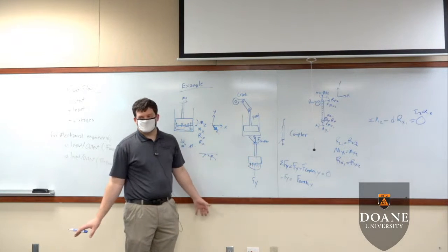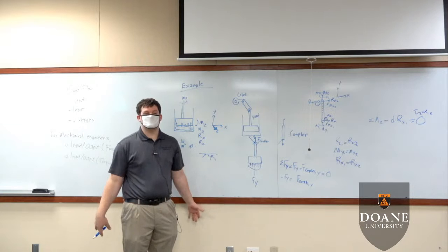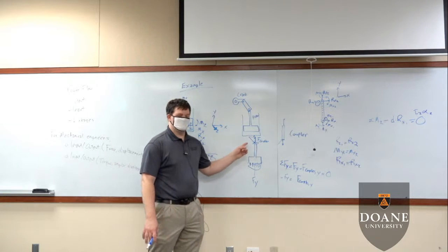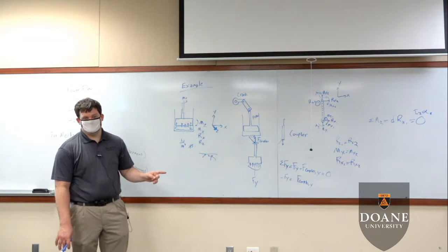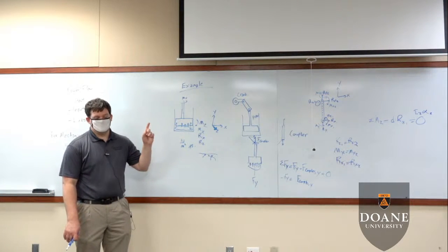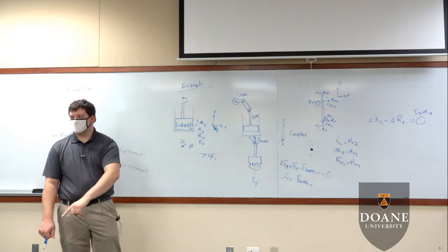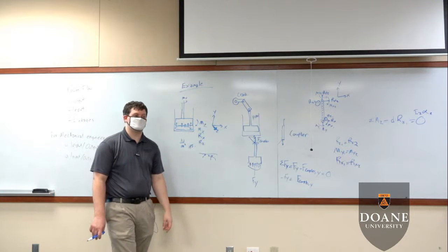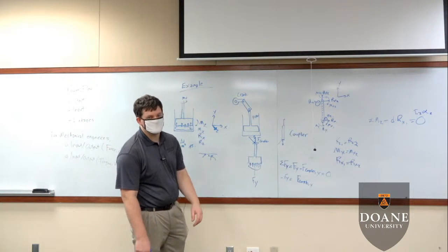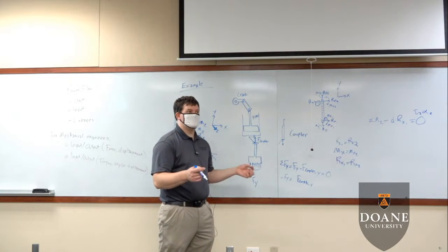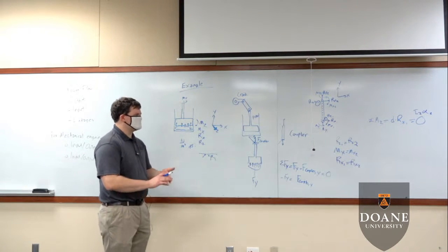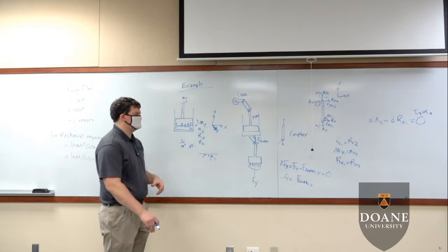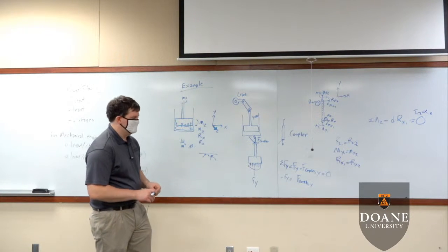So, there is a caveat there. While the force does increase, if this mechanism is not moving, the force increases substantially. If the mechanism is moving, it no longer has that same transmission just because there's inertial resistance, which is actually nice because it limits the amount of force that gets transferred. Okay, but this is another reason why power transfer is such a complex system.